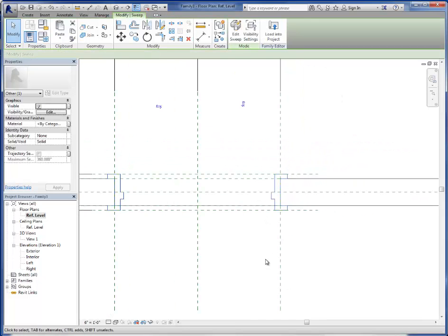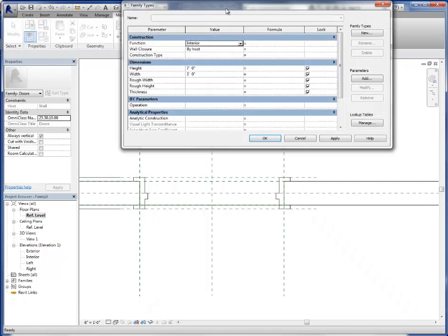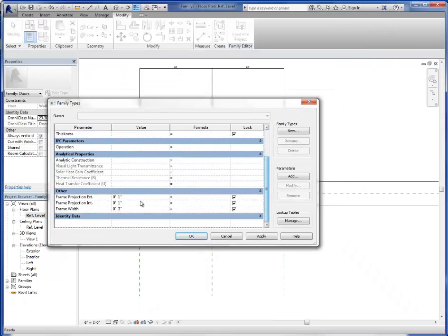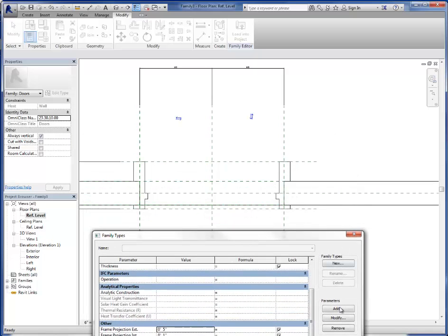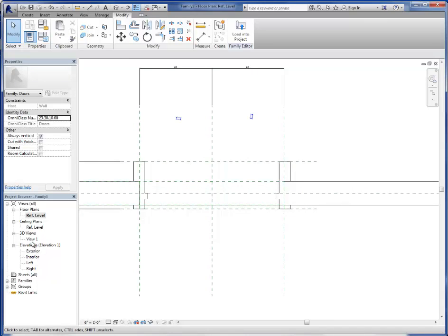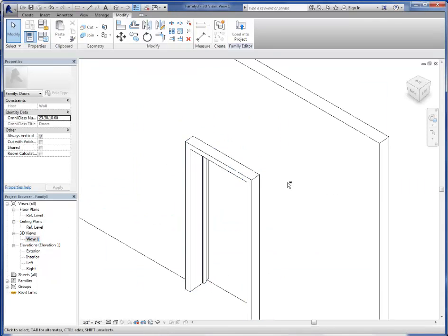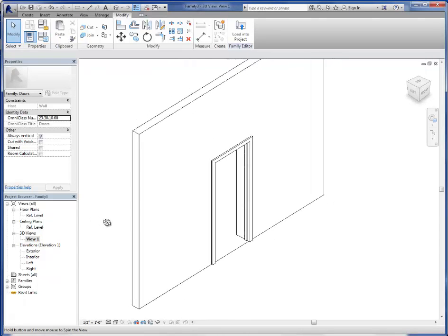Done. So what that enables us to do is as we come in here, we can click on this guy and pull up the properties. We can start to adjust the frame dimensions on these guys. So we hit apply on this. Set that to 5 inches. You can see that the geometry of the sweep actually will move along with that parameter, and this is the really cool parametric component of Revit in here. Okay, and so we've gone ahead and created that sweep really, really quickly.